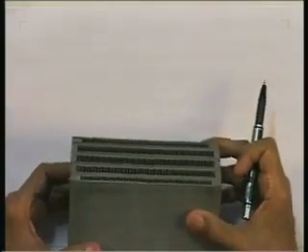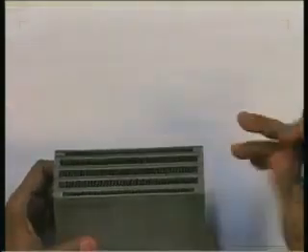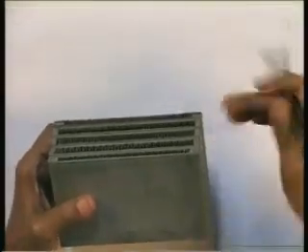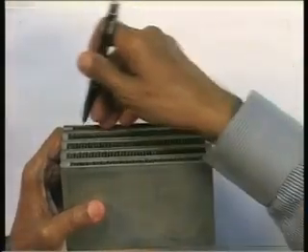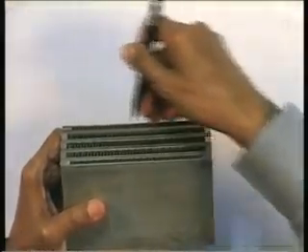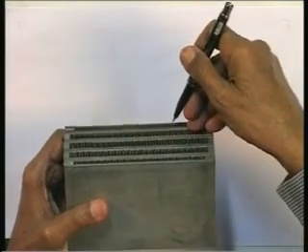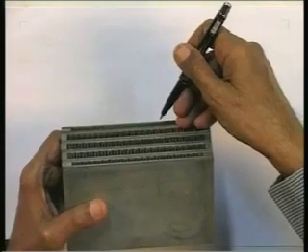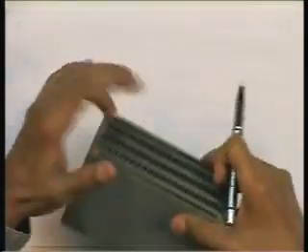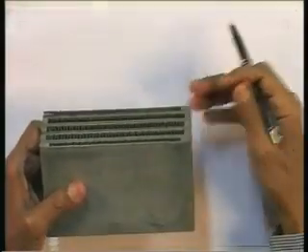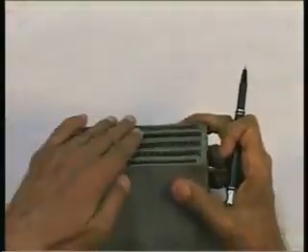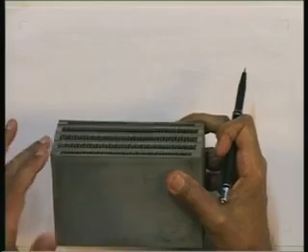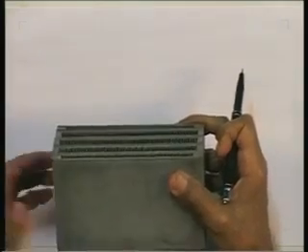this. Now, suppose I do not have fins on both the sides, but I just have parallel plates. Then in that case, a hot fluid entering in this channel can, while flowing through, also move in this direction and mix with itself, in which case we will say this is a case of single pass cross flow, both fluids mixed, because there are no fins on either side, the fluid can mix with itself. And if I have fins on one side and no fins on the other side, then it will be a case of single pass cross flow, mixing on one side, no mixing on the other side.